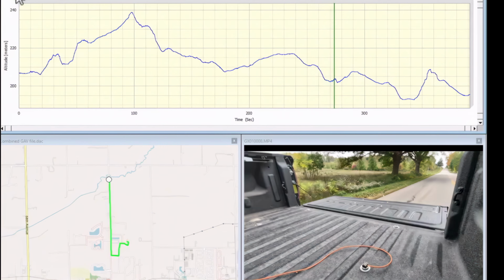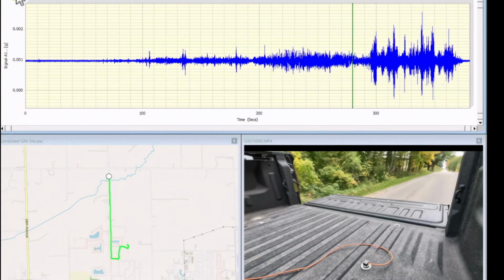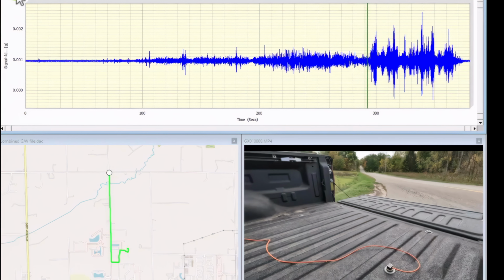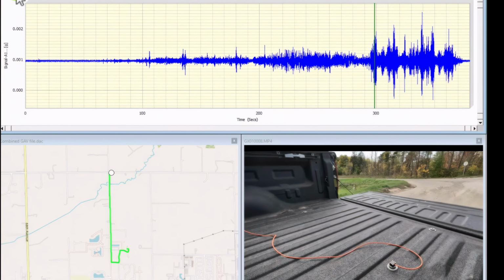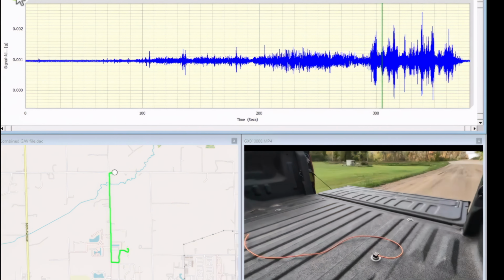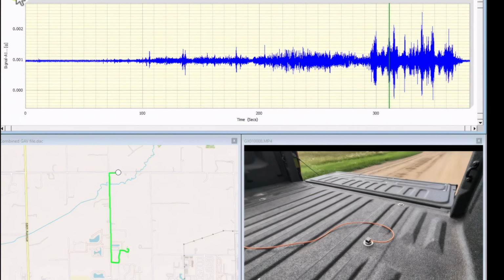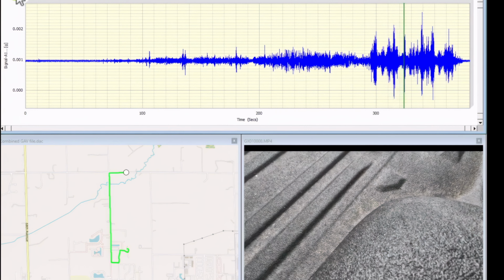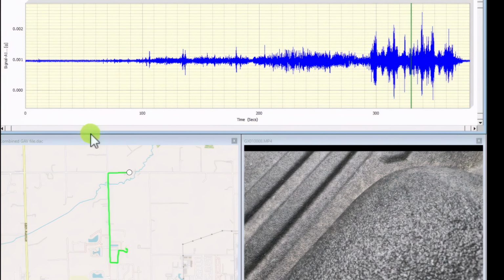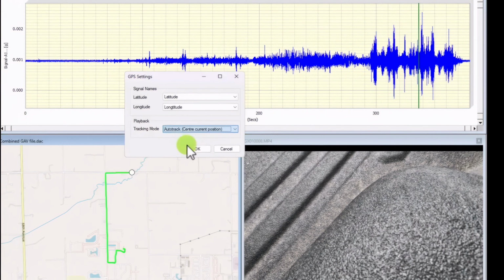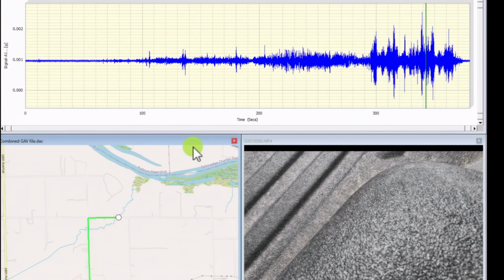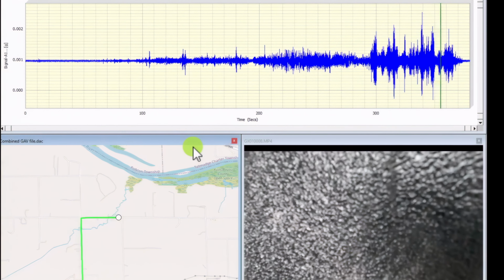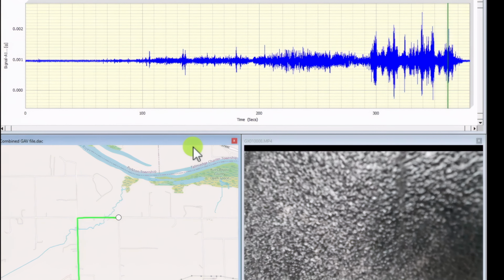I think the key thing is to start the vibration recording and the GPS recording as closely as possible. I didn't have to do a lot of data manipulation in CSV to get the timing set, but basically you would just delete the number of rows that you didn't need in order to sync up the data. But within 1 second of starting both devices, I didn't really have to worry about it too much.